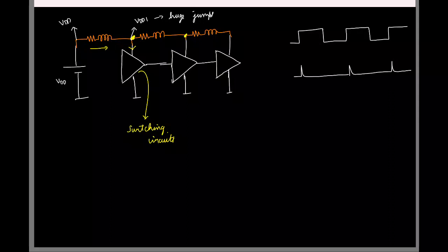Like in words. The issue is the fact that there will be spiky currents, and the problem now is these currents seem to be flowing through this path. So what could be a solution in words? It should not pass through that path. So you should provide some other path for those spiky currents to flow.